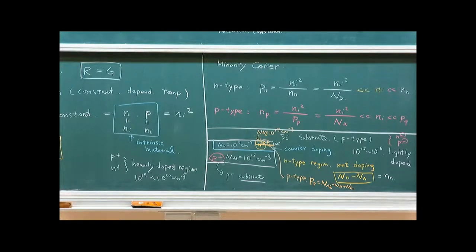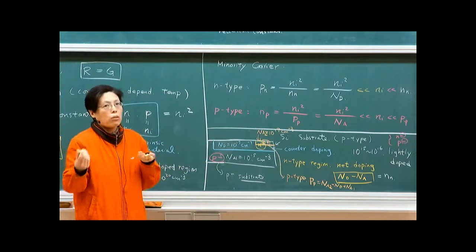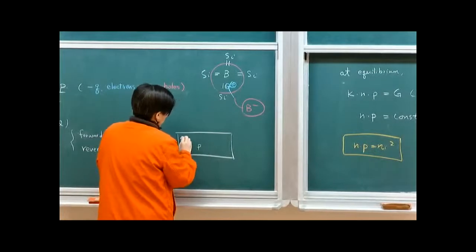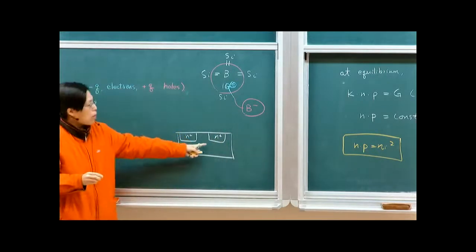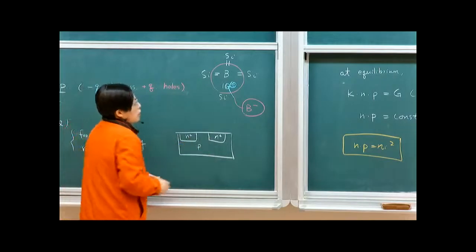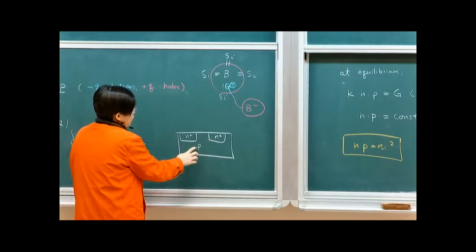The key thing to take home is that you need to understand what plus means. It is simply referred to as a heavily doped region. Minus means lightly doped region. And if I just simply label it N or P, it will simply be middle-range doping. So then you'll be able to read something like this. For a MOS transistor, it will be something like this. It would be an N plus, P region, N plus. You will know that you start with the P and then you have two contacts with N regions. N plus meaning that's heavily doped. Okay? So once you see the structure, you get a sense as to these are the counter-doped regions and these are the basic substrate.